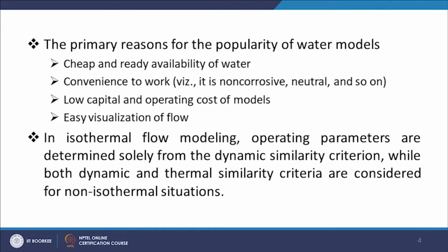So, in isothermal flow modeling, the operating parameters are determined solely from the dynamic similarity criterion, while both dynamic and thermal similarity criteria are considered for the non-isothermal situations.